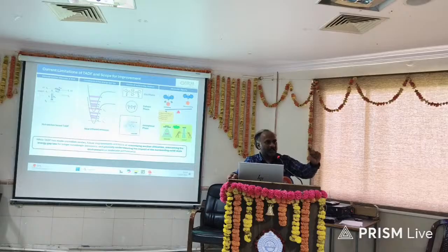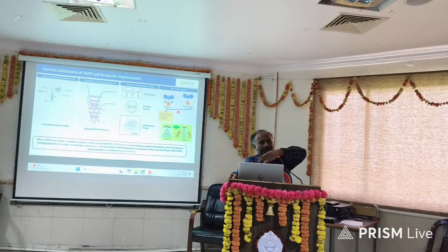It will emit in a certain region. You have 10 to the power of 23 molecules, so not all molecules will release the energy at a time. Some molecules release now, some release later. So you don't get a short emission peak, you get a broader emission peak. So that decides the color purity.